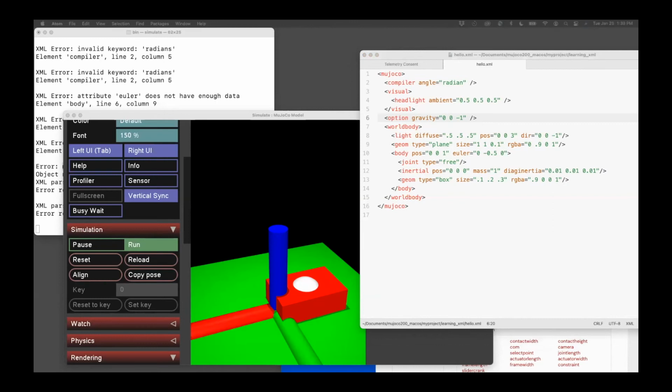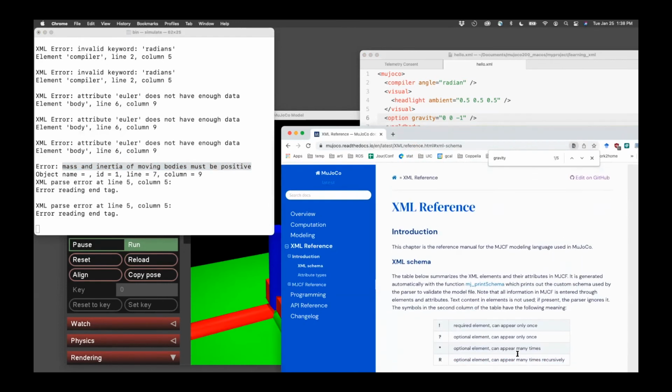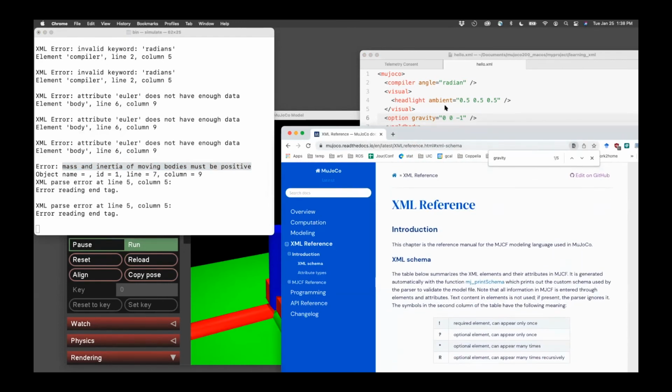Okay, so moving on, there's this thing which is very useful. It's called asset. I don't know if you know, but in URDF, you have this thing called Xacros. Xacros are things where you specify, let's say radius equals 5, and then you can use that R value in a bunch of places.